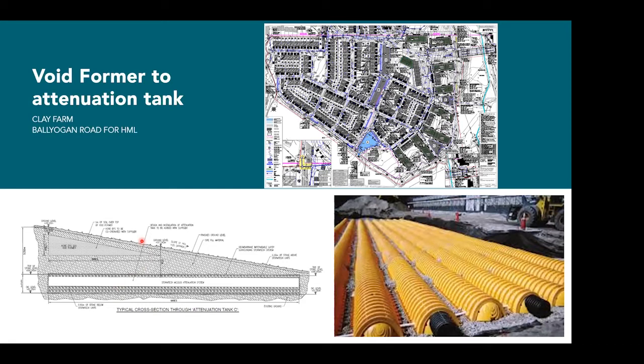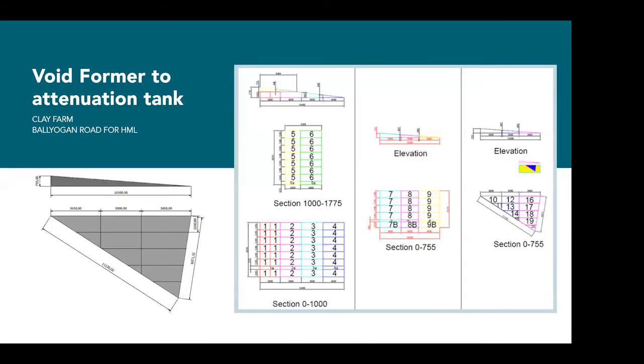Obviously, if it's very, very highly loaded, we can go higher again with the different grades of EPS all the way up to EPS 300. So when we manufactured the material, again, it's very specific to the site. And again, to make life very, very simple for the contractor, we would provide them with drawings, a breakdown of the material, all the pieces numbered. Again, it's an installation drawing, and very, very simple from the site point of view to actually place, because it's a lightweight material. Even in large blocks, a lot of the time it can be manhandled into position.